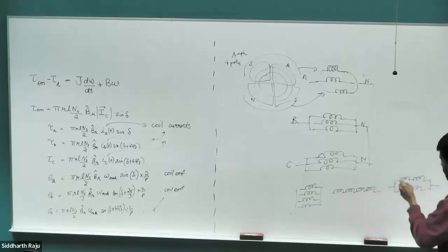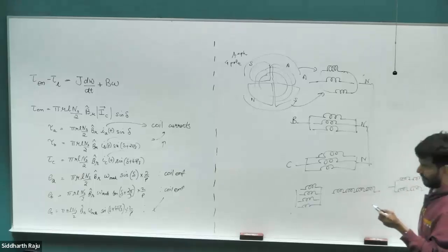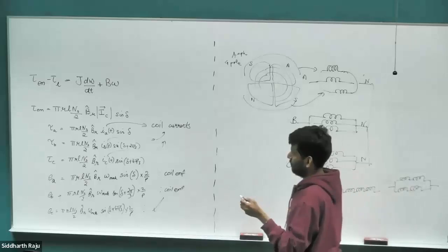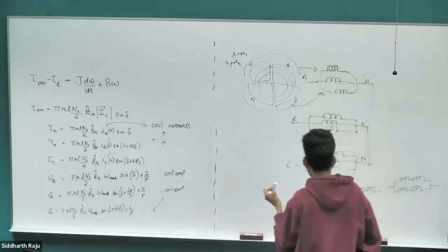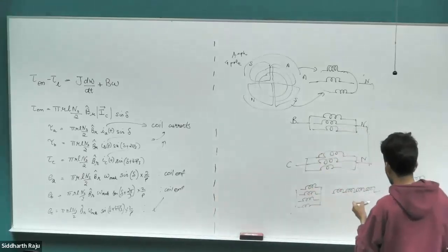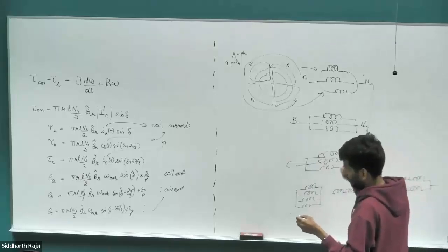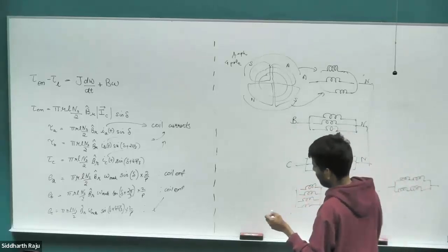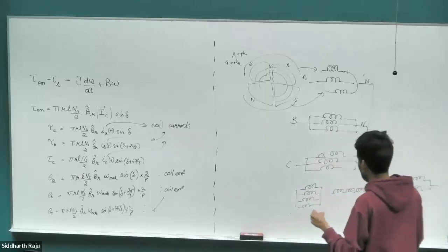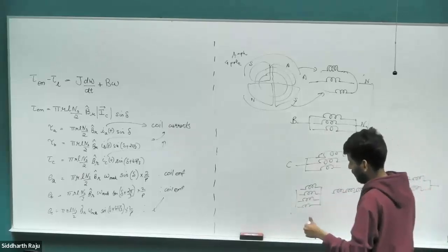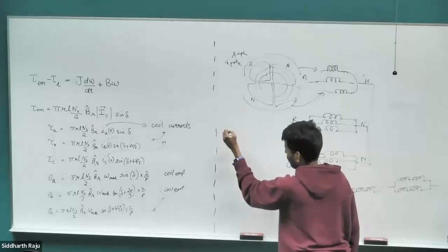Of course, you wouldn't want to do 3 of them in series, 1 of them in parallel. That will again make it an asymmetric distribution, which would then cause the space vector to not trace a circle. So there are 3 possibilities. When you go to a higher number of poles, you have more combinations that you can create out of them. So, irrespective of the number of things, let's classify this with 2 terms that we are going to introduce.